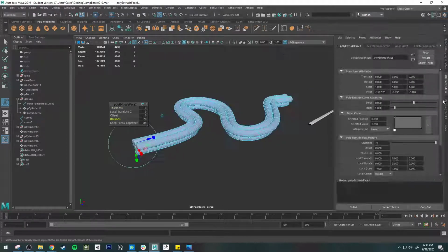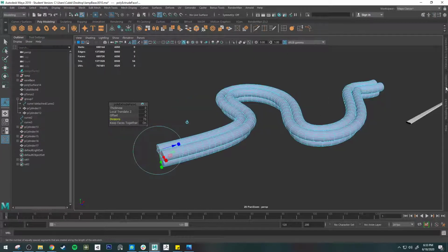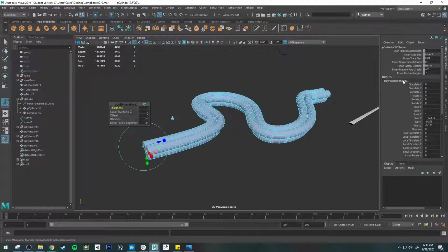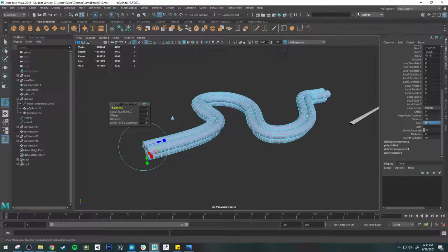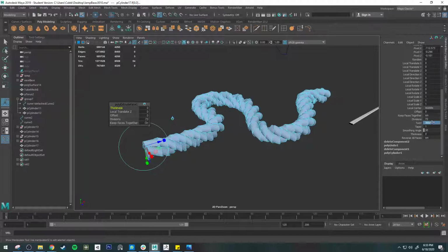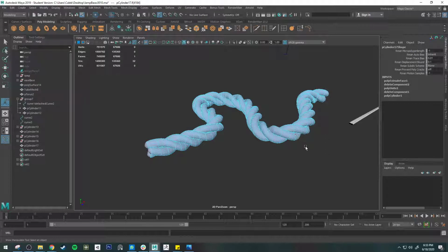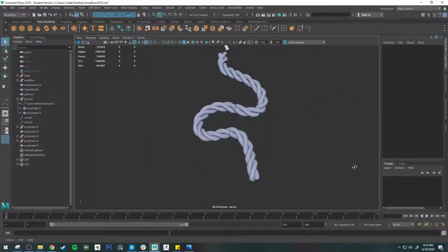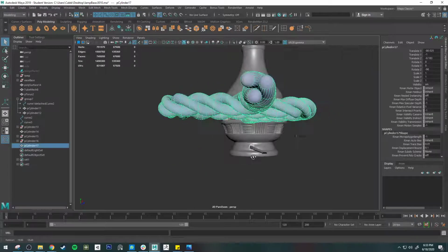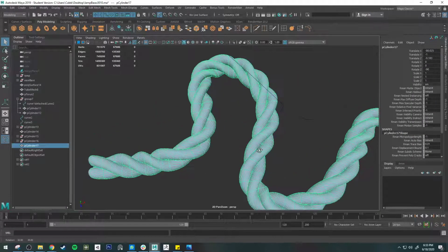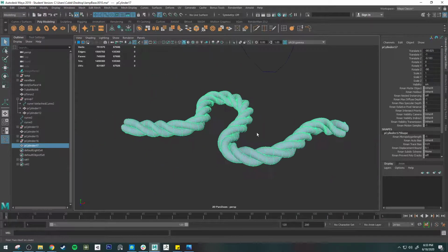Okay, and then same thing, just go ahead and increase the subdivisions to a higher number. And then what I can do is start twisting it. Set this to like 8,000, too high, 3,000, and that's looking pretty decent, right? And I probably would want to start tweaking and modifying the actual shape, right? So instead of having these separated like that, what I might want to do is have them intersect a little bit.